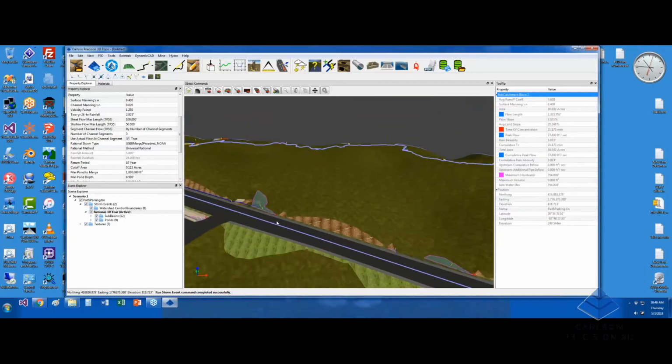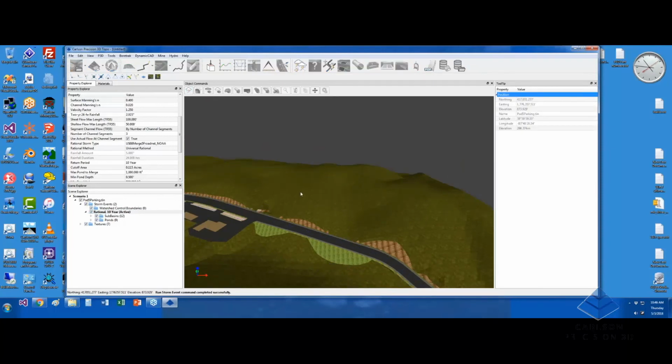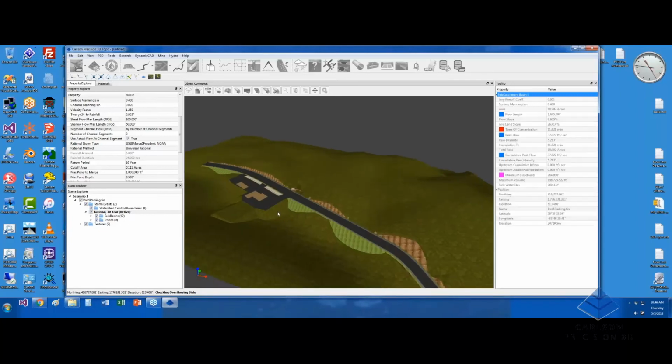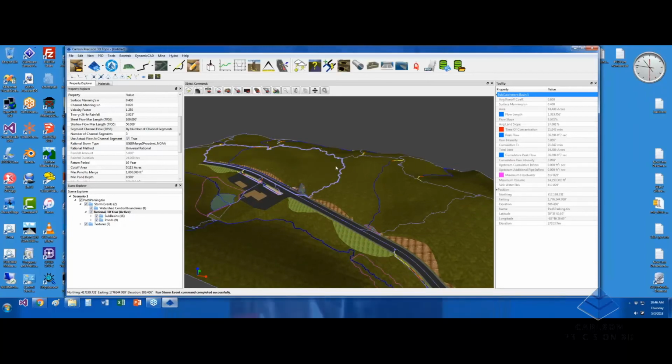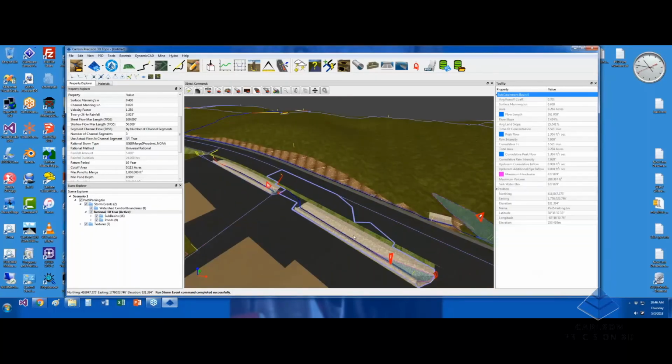And so I've modified those. Now what I'm going to do is recalculate the storm. And what you'll notice is that I have more subbasins that are going to be created, and it's going to isolate those pockets of ponding to smaller sub areas. So now you can see we've got a separate subbasin here. We've got a separate subbasin here. And if we come down into this roadside area, you notice that we've got a separate small sub-catchment basin here and one here.